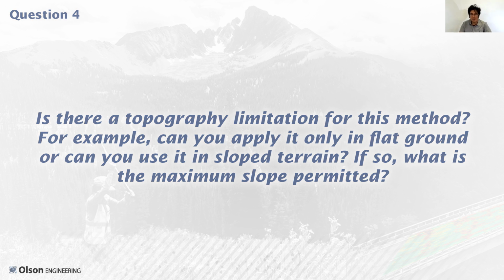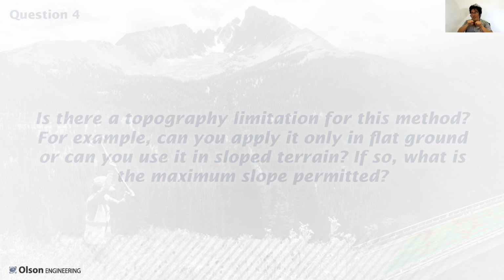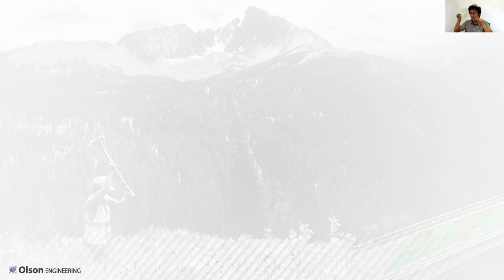The big thing is if you're in a situation where you've got a bunch of hummocky hills, you can't have one receiver at the top of each hill. Then you're going to get some weird results. So you want to have a receiver density enough that you're characterizing the slopes of your surface.